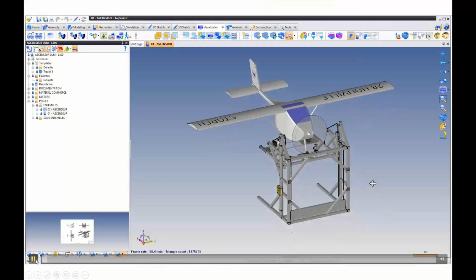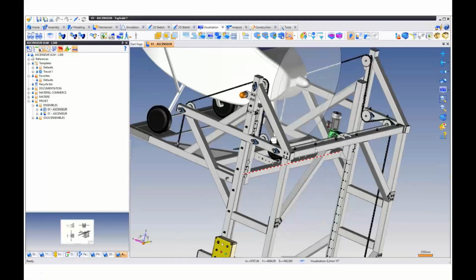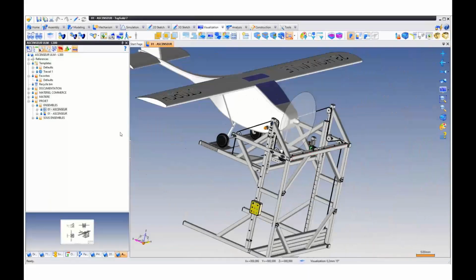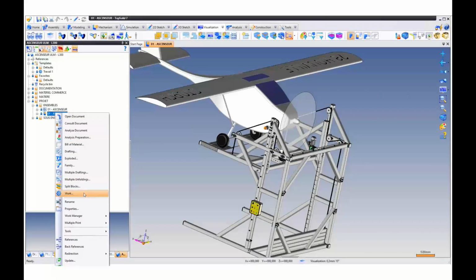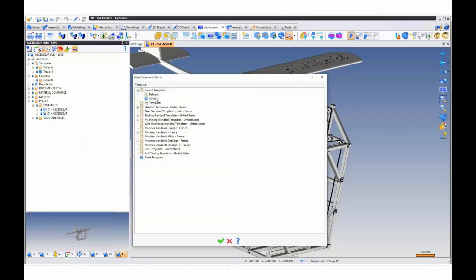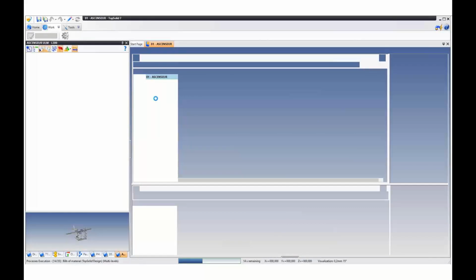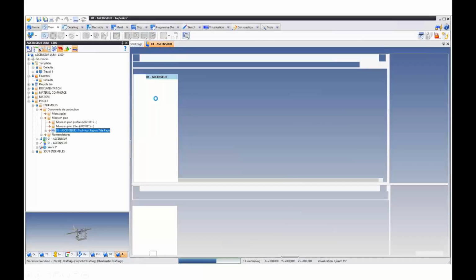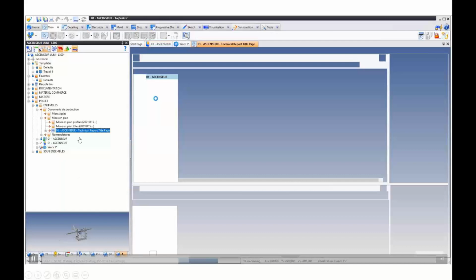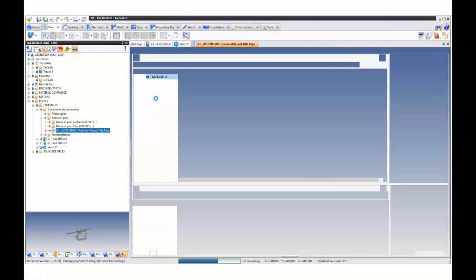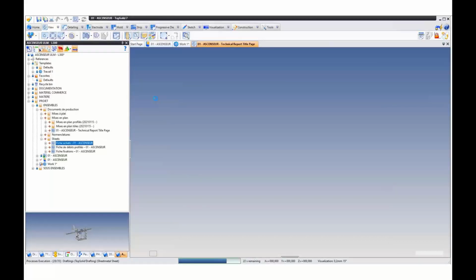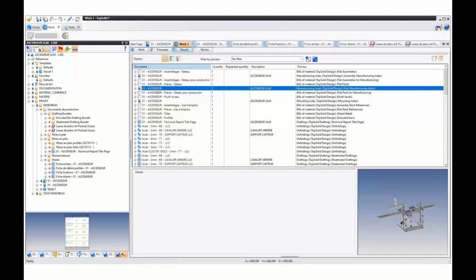So here we're going to create some automatic documents. Okay, so here we have this assembly for this little plane. We're going to run this work document, and here you're seeing some automation running. And if you look down here, it's building a lot of information. Okay, it's building drafting, it's building bill of materials, it's doing a lot. Okay, and again, the video is not sped up. This is real time. This is just doing all of the heavy lifting for you.